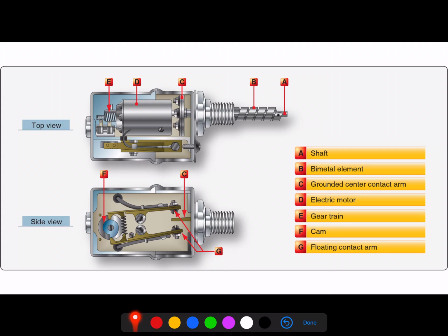So as we talk about the position of these cooling doors, I want to touch briefly on our floating control thermostat. This is an analog device. It's an older device. Most newer aircraft are going to use a more complex system than this for regulating the position of cooling doors. But in all reality, that door position can be regulated from something as simple as a manual control in the cockpit all the way out to a fully electronic system that's taking multiple readings and adjusting how this operates.